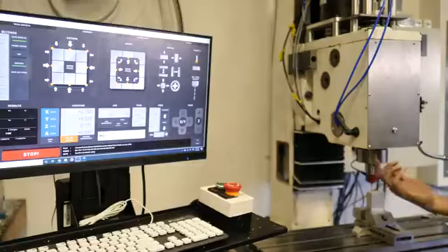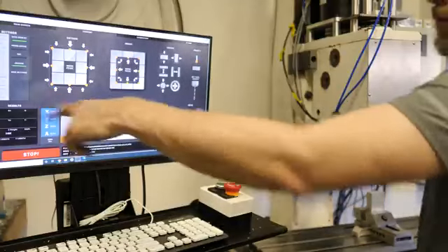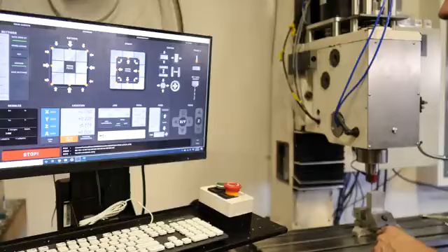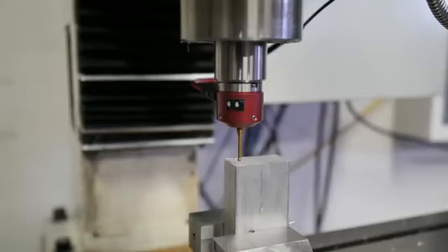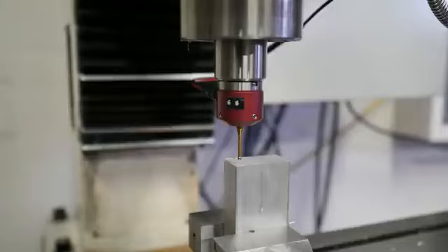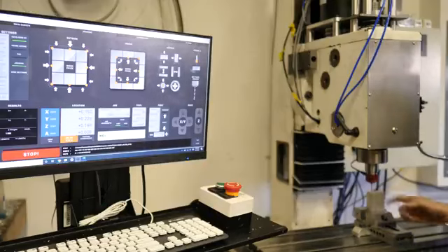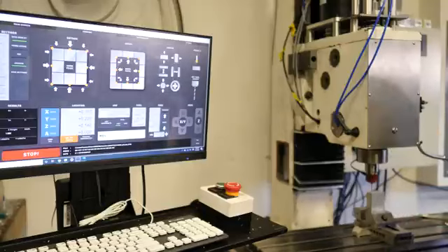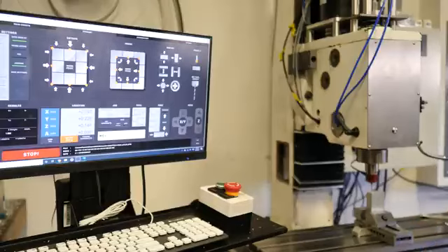It's above the part. You just have to be somewhere above the part. It will give up after its search depth, which is 0.4 inches at the moment. Click the tool, the probe Z, it's going to go down, it's going to measure it, it's going to measure it again at a slower speed, and it'll even go back to where you set it initially, which is pretty handy. And there you go. You've got your full datum set to the very corner of this part. By the way, both of those buttons that you need to do that are on the main screen as well. That's why I put them there, because that's how I set up most of my workpiece datums.